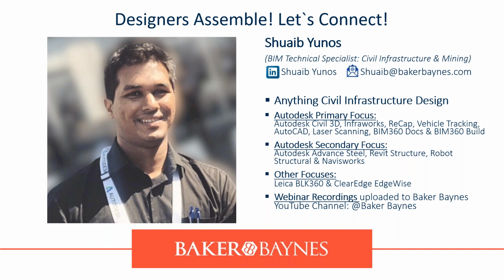But if you generally link in your GIS, you can actually run a query and check it out, like you said. That's the best way currently, using the Map 3D engine. Unless you've got ArcGIS Online, maybe you can check that and link using the Esri Desktop Connector or the built-in connector for Civil 3D and InfraWorks. That might actually give you an answer. But as far as I know, the query and map edit functions are the best way to go and a much simpler way to go.